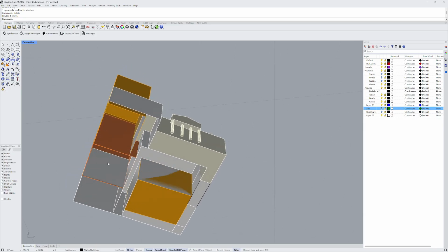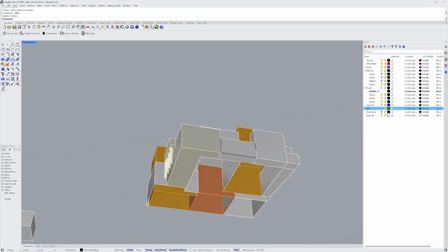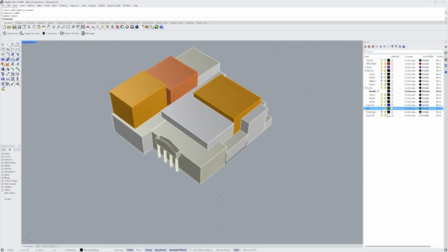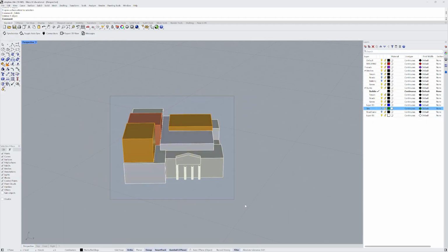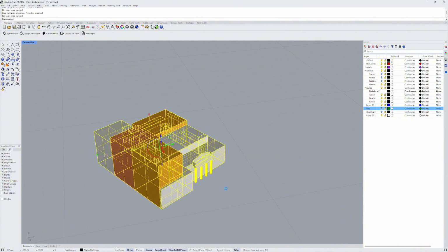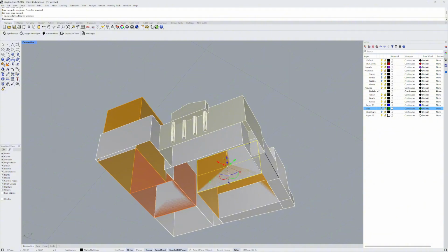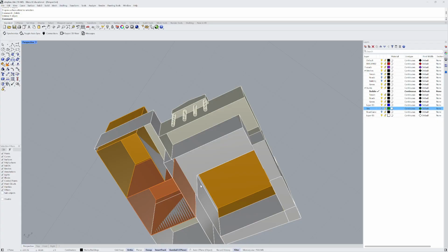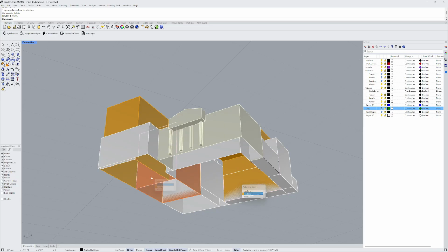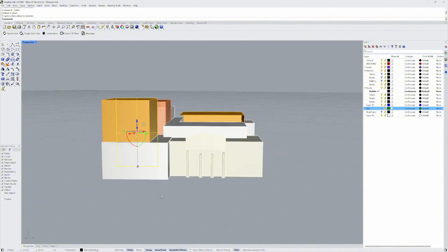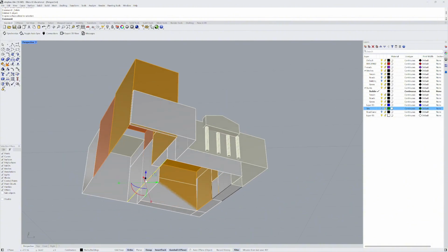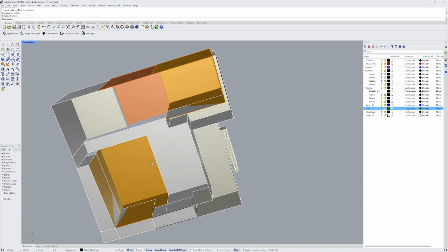Just see, yeah, there's quite a few that are intersecting. Just here, just get rid of these. It's going to merge all the coplanar faces. And to make sure that there's no difficult faces in there. And then what I can do is just delete away some of these ones. I'm just going to take away all the internal faces. Just keep the outside ones.